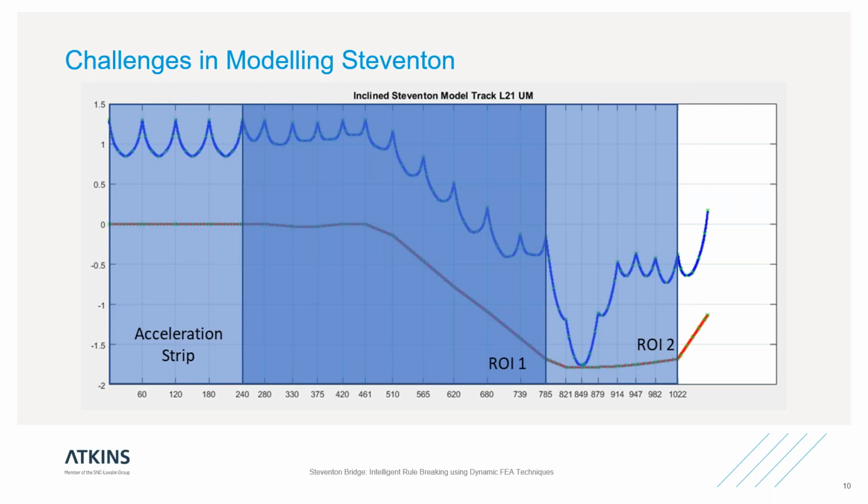However, while there wasn't any electric test train data for Steventon, there was plenty of data at other locations on Great Western. So the challenge there was to find a location that looked like Steventon, with a level crossing and a bridge close together and a gradient in between that had been subject to high-speed physical tests. And we found a very suitable location quite nearby, a place called Knighton, where we have a level crossing and then fairly shortly followed by an overbridge.